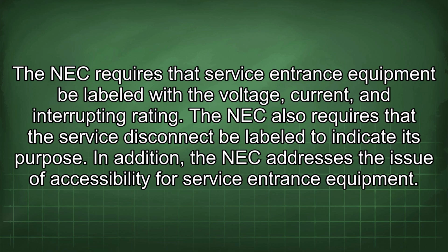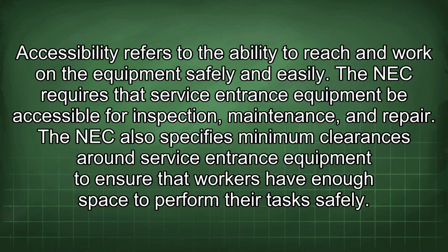In addition, the NEC addresses the issue of accessibility for service entrance equipment. Accessibility refers to the ability to reach and work on the equipment safely and easily. The NEC requires that service entrance equipment be accessible for inspection, maintenance, and repair. The NEC also specifies minimum clearances around service entrance equipment to ensure that workers have enough space to perform their